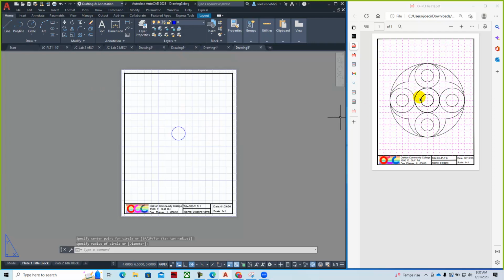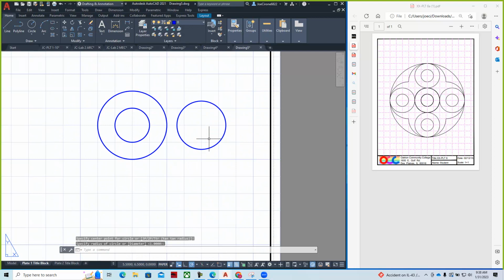And then basically we'll go into the drawing and create the geometry for that. And so I'll create a circle like this right here. Create another circle. Circles work best when you draw them from the 12 o'clock position. And so if I go like that, or 3 o'clock, if you go on an angle, then they're not going to be on the grid. And so if I click on this and I hover over a grip, you can see the geometry settings for those. Just little tips and tricks as we get better with it.